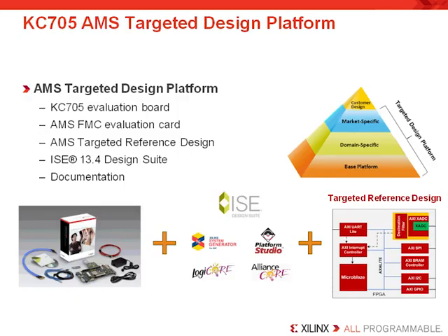You can begin to evaluate the XADC subsystem today when you use the Kintex 7 with the ISE 13.3 Design Suite software. The AMS targeted design platform includes a targeted reference design so you can see how this feature works and how to get your design started right now. Now look out for the AMS demonstration recording, which will give you an overview of the AMS targeted design platform and the targeted reference design, which can be used to evaluate the XADC block on the KC705 demo board.